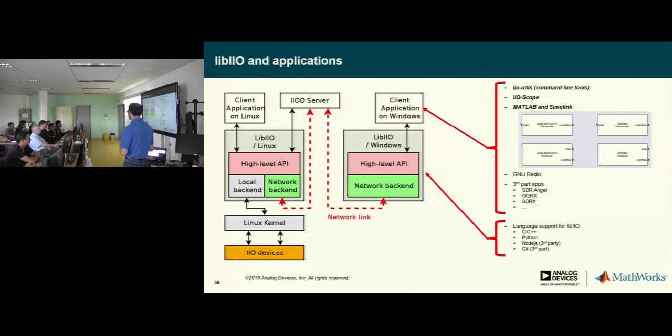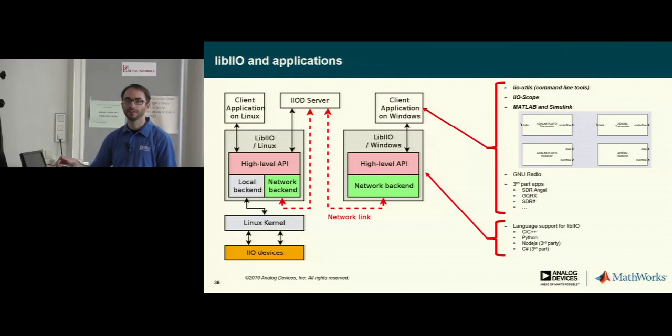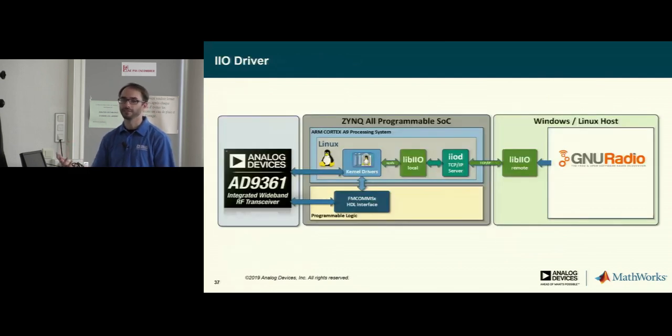But as I mentioned, this is really the low-level pieces that GNURadio is using to interact with a device. So if you take our generic blocks that are in GNURadio, you can use them to add additional settings that might not be in our Pluto blocks. So if you want to change some bizarre setting that's in the AGC that no one would want to change, but you want to do it, you can do that through our more generic interfaces in GNURadio. It's a very extensible way to get at the driver.